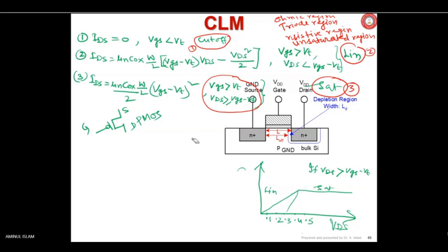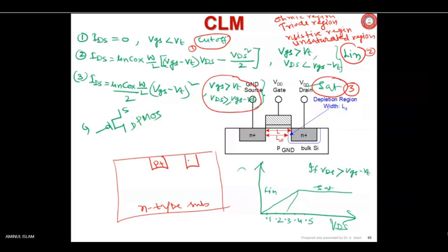And we have not at all discussed P MOSFET. If I draw the structure of a P MOSFET, you take the substrate as N type, okay? N type substrate. In this, you can make P plus by implanting it with boron, and it has become P-type now.